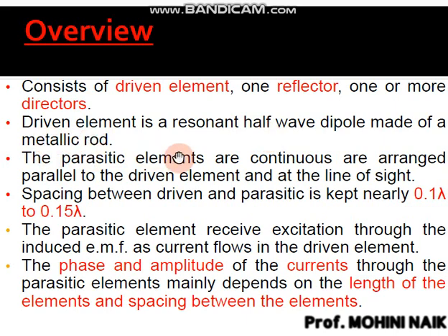There are equations given, don't worry about this, but this is just for reference that it depends upon the half wave dipole. Dipole basically means a rod kind of structure. The parasitic elements, parasitic meaning all the directors which are present now, they are continuously arranged, meaning in one line they are arranged parallel to your driven element and to the reflector.